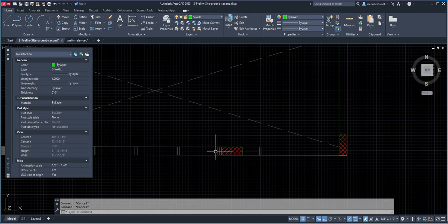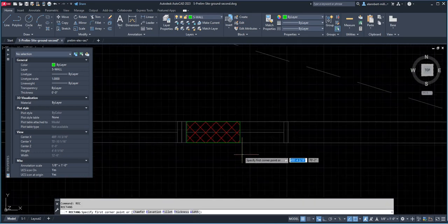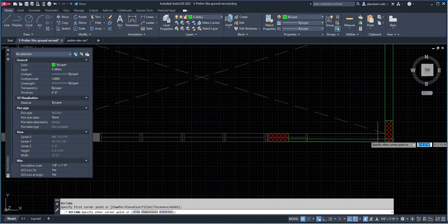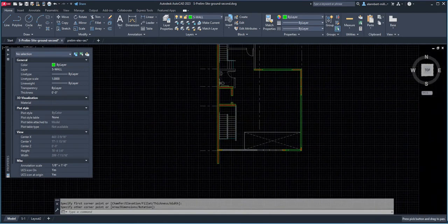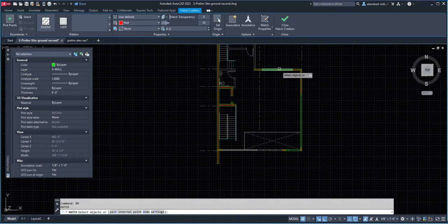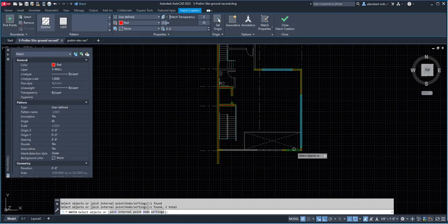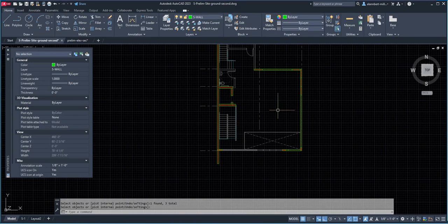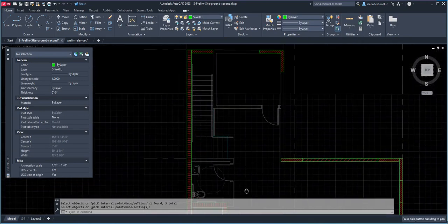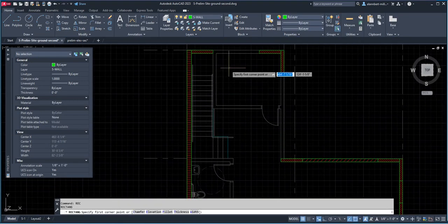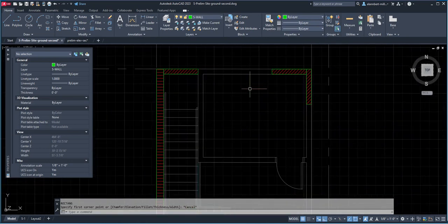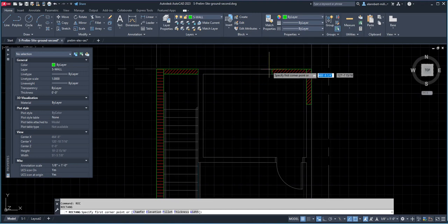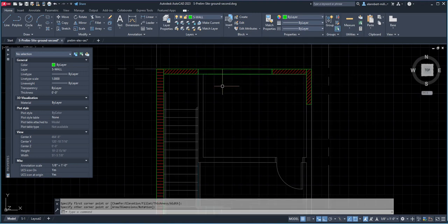The windows, okay, because the engineer has to block that off. So let's do a hatch. We're going to select this and this and this. Okay, and then let's move on to this side. So I just use rectangles, but like I said, you can always use a P line.